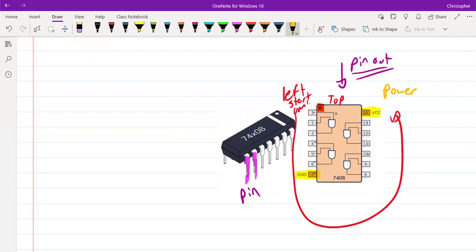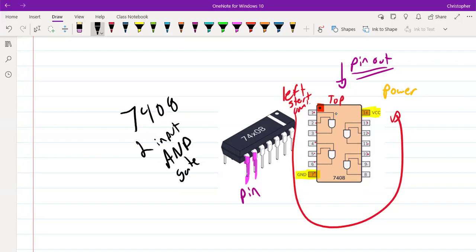And then all of these circuits, the list, 7408 is a 2-input AND gate. And they usually say this is a quad 2-input AND gate. Why is it going to be called a quad? Is we see we have 1, 2, 3, 4 AND gates inside this one chip.